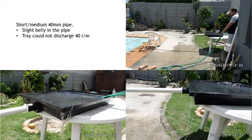Here's a 40 mil pipe, straight out, medium length. I'd say, what's that, about 4 meters? Slight belly in the pipe. There's that belly. You can see it there between the chair and the tray. So if you were to measure the fall between the outlet of the tray and the outlet of the pipe, there would be a fall. It would be lower than the outlet of the tray, because that's what you hear all the time. Yeah, but there's a fall. The outlet is lower than the tray. Yeah, but there's a belly in the pipe.